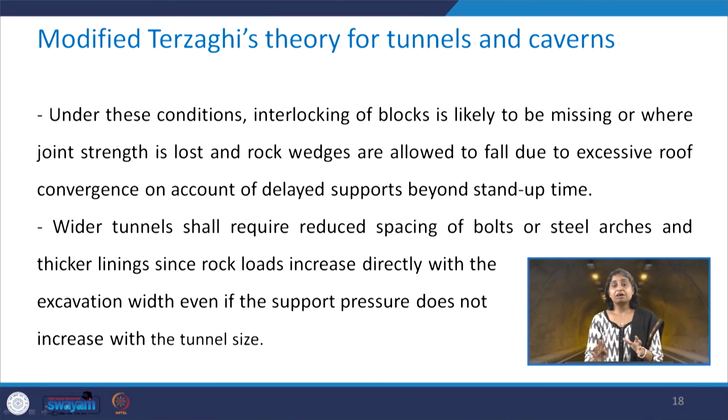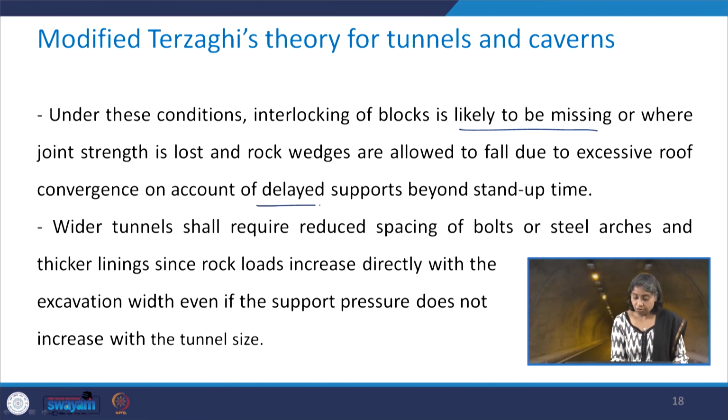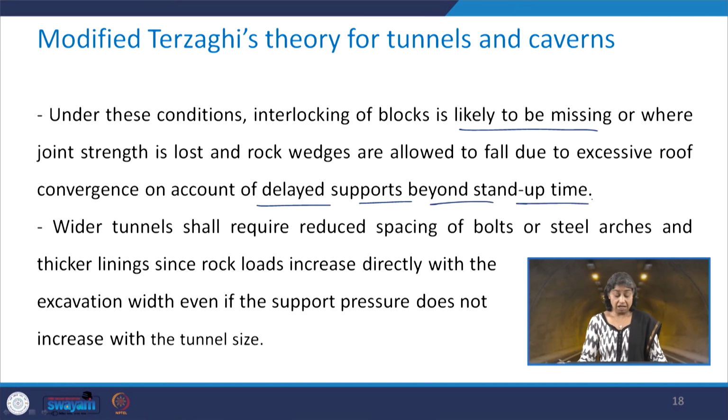Now, if such conditions are there, interlocking of the blocks is missing, or the joint strength is lost and the rock wedges are allowed to fall due to excessive roof convergence on account of delayed supports beyond the stand up time.